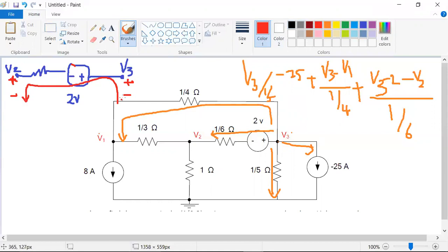While the current is flowing like this, I am writing the current equation I equals, in terms of V by R itself, right? So for the numerator, I need to consider V. For the denominator, I need to write the resistance. So for writing the numerator, how is my current traveling? My leaving sign is positive, plus V3. I always follow the leaving sign from day one. I set the rules.